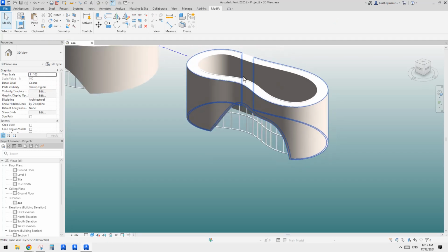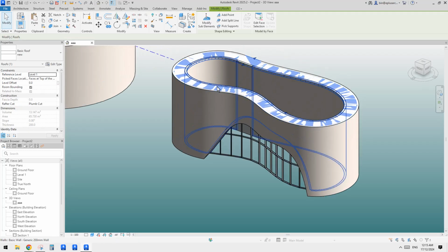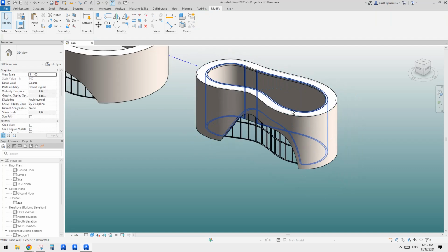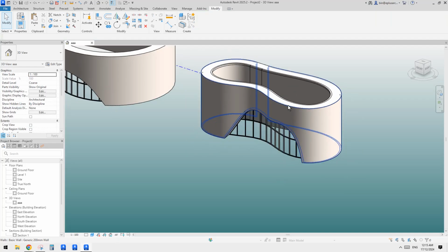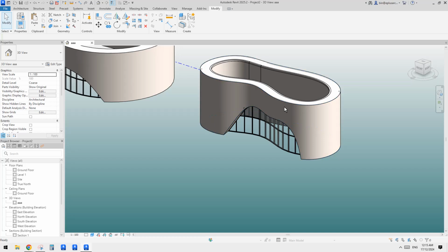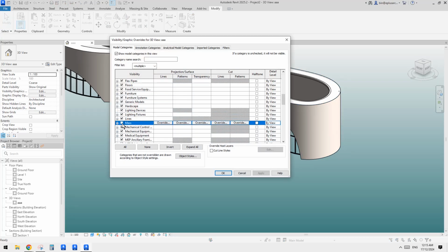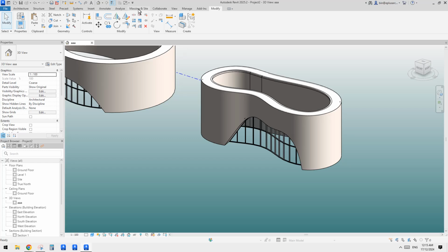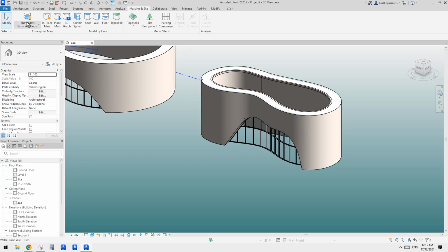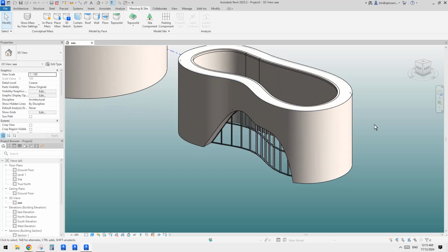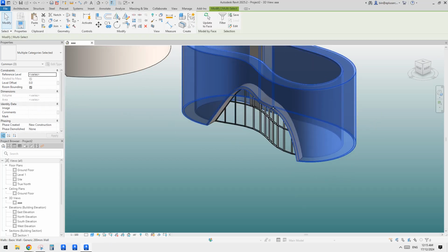It's gone. But the other mask is still there, right? If you want to hide them, you can select it, EH, or, currently, let me check. If you type VV, it's already invisible. But I think what makes it visible is this one. If you go to masking and site, this one means it should always show mask. So now you can just untick it. It will hide the mask, so it's not there anymore.